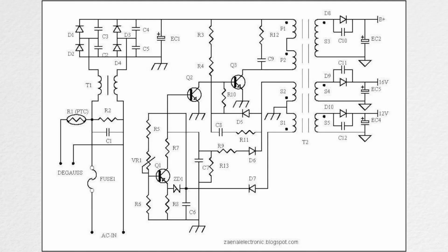Now let's take a look at the switching power supply schematic. As you can see, this is a little bit more complicated, and it's going to be beyond the scope of what we discuss, except for the fact that in a switching power supply, the transformers being used are a lot smaller. The reason is that we're using power MOSFETs to switch the power on and off super fast.